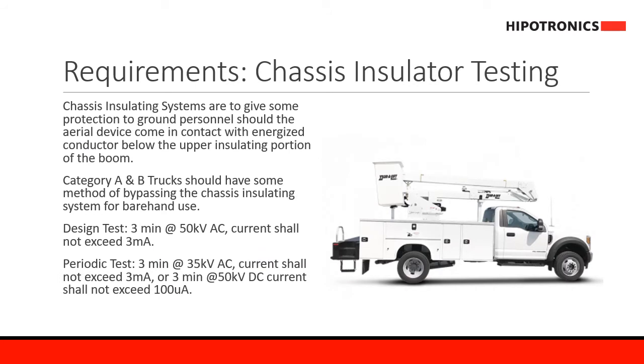Chassis insulators must also be tested to ensure safety to those working near the vehicle. Chassis insulating systems are to protect personnel if an energized conductor comes into contact below the boom insulation. Chassis insulating systems have both design, quality, and periodic testing criteria as well.